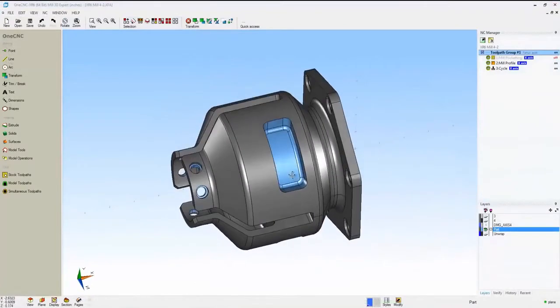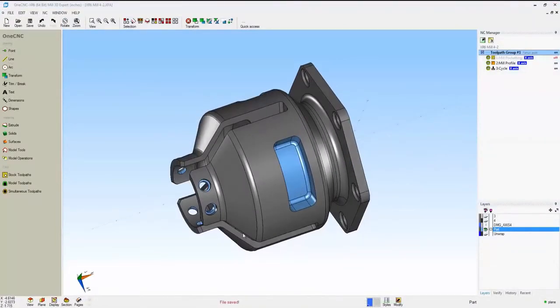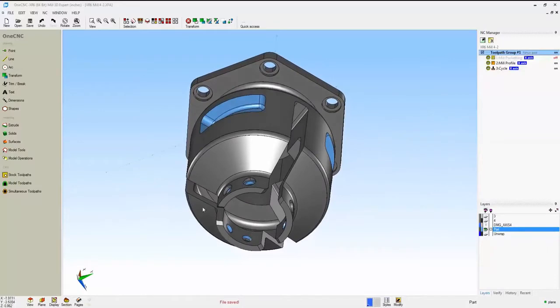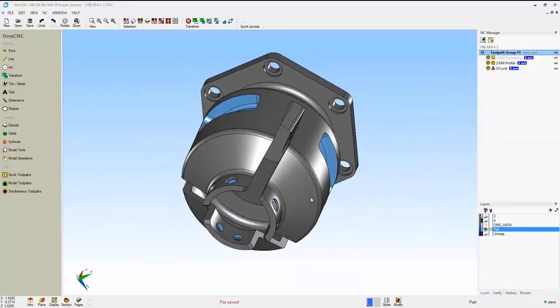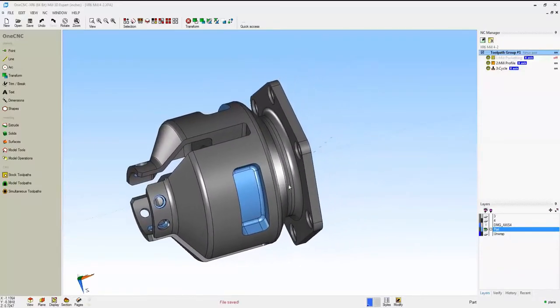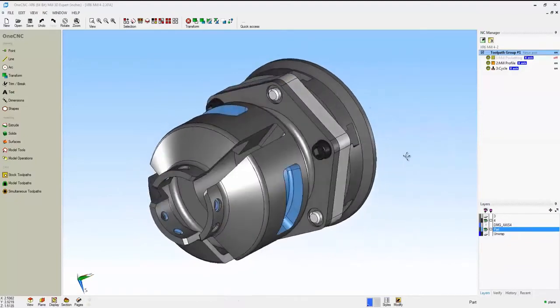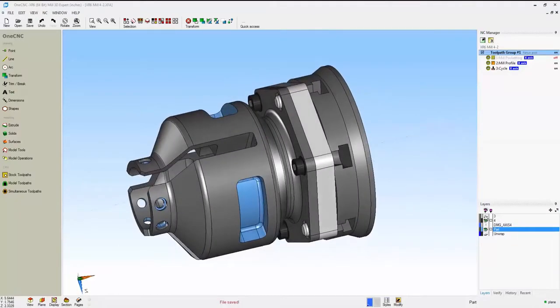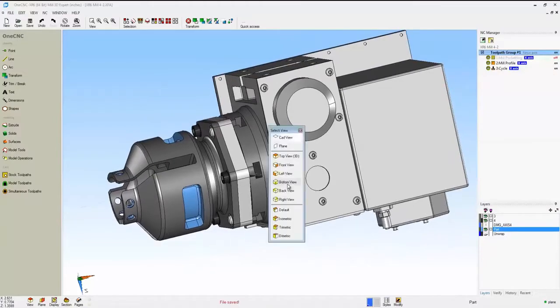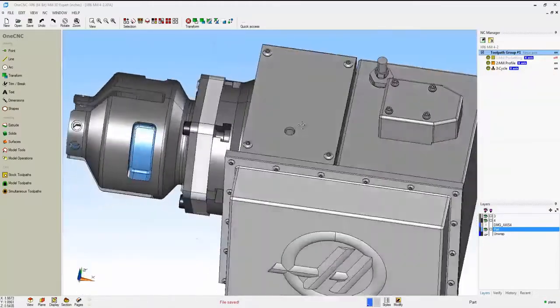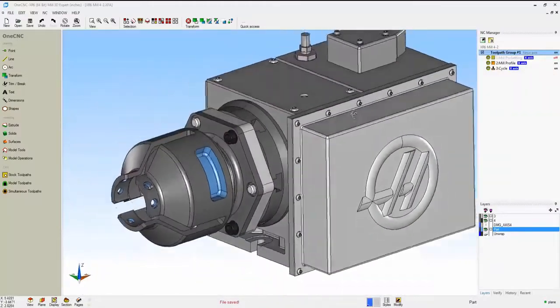This is a little bit different. This is where you've got geometry wrapped around a cylinder. In this example, I have some pockets wrapped around the cylinder, and I also have some holes wrapped around another cylinder there. Alright, so what we do is we unwrap that and then machine. We can add our fixturing. Again, everything that rotates around the 4th axis on layer 4, everything that's stationary on layer 3.